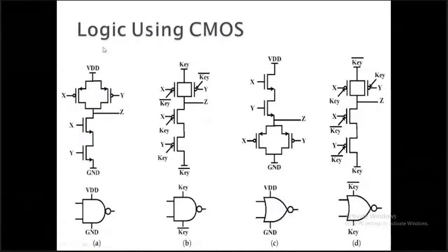So if we want to calculate the leakage power for the circuit, we will put one load at the output, and then we will put some conditions here. Like we will take any one of the states, both inputs are in zero case, and output Z is based on the input 0 0. It will be 1 or 0 based on that.